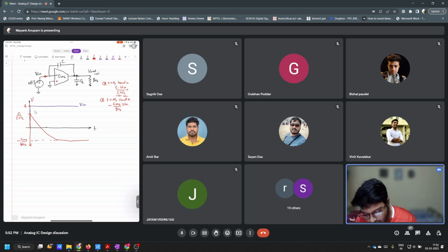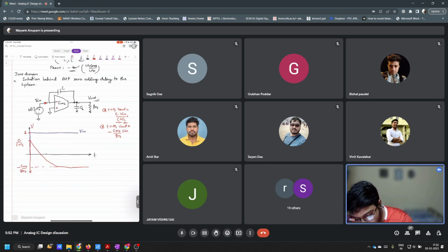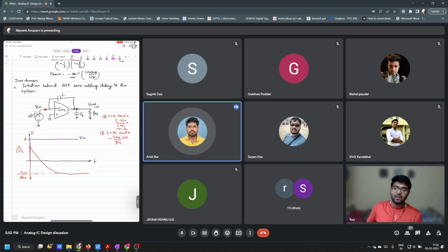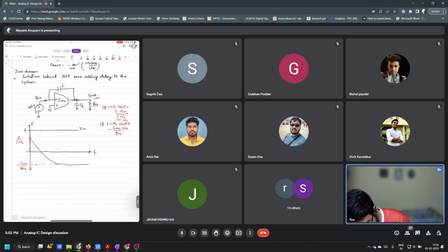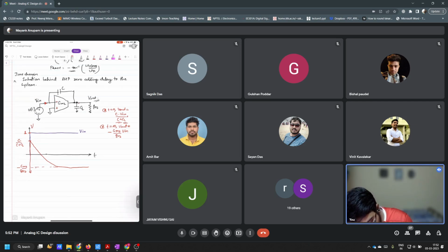So now can you understand? Now can you see what happened here because of the 0? Can you clearly see there was some delay? Output is lagging the input. And ideally, what did you want? Because of this unit step V in, you ideally wanted your system's response to be equal to minus GM2 by GO2 instantaneously. If the system would have jumped instantaneously to this value like this, then this was an ideal response without any delay.